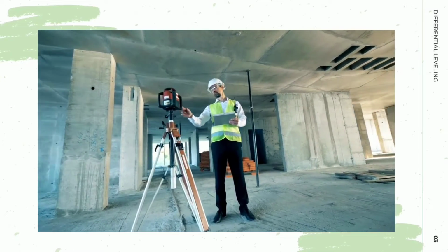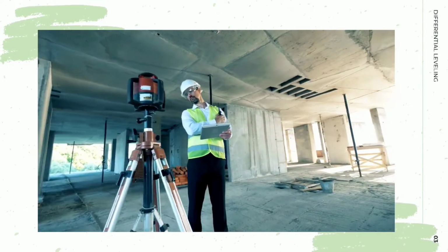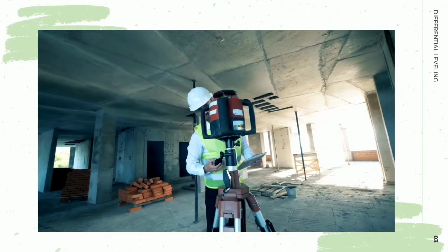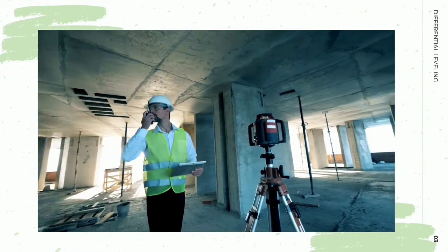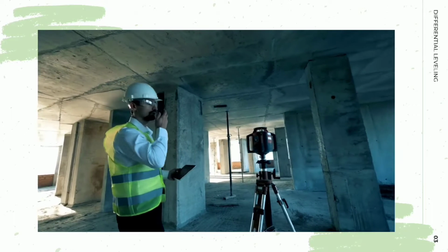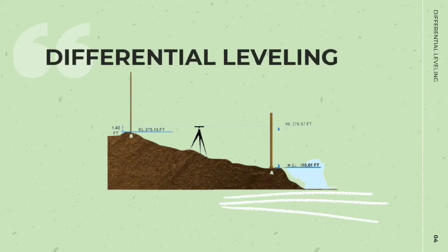Preventing costly delays and achieving the desired outcomes and precision requires a thorough understanding of leveling concepts and the right application of the procedures and equipment. The preferred methods of obtaining elevations are, first, differential leveling. It controls benchmarks, cross-sections, and point elevations.